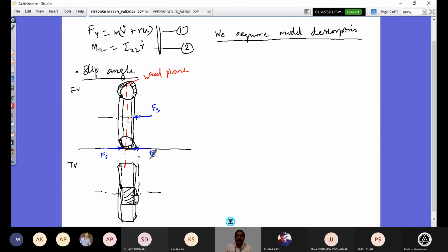If this system is equal, nothing happened. So this balances, and I have this. And these two are of same magnitude and opposite sense, creating a couple. And that couple makes your tire wheel get a pressure on the hub, right? So when side force is acting, the tire wheel assembly gets a pressure on your axle hub. So that's a necessary couple.